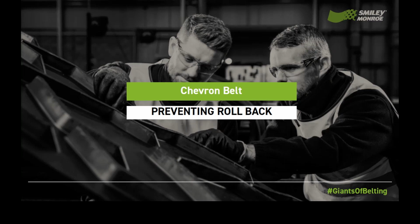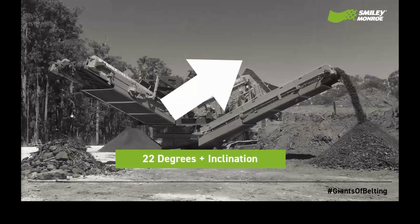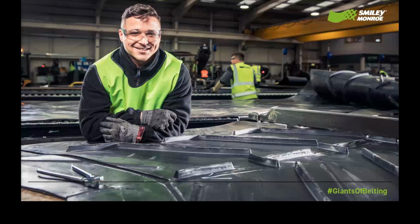Thanks, Alicia. Flat conveyor belts with a smooth carrying surface are useful for conveying of packed and unpacked material up to an angle of inclination of 22 degrees as the upper limit. Chevron conveyor belts are the right belts to meet the requirements when higher angles of inclination are required. Chevron conveyor belts have rubber profiles that are integrally vulcanized with the top cover of the belt.